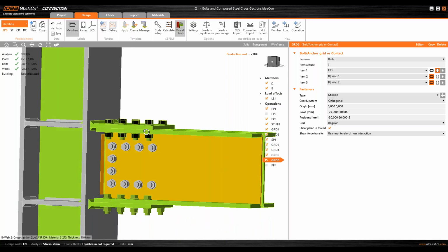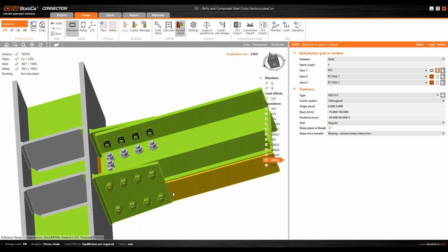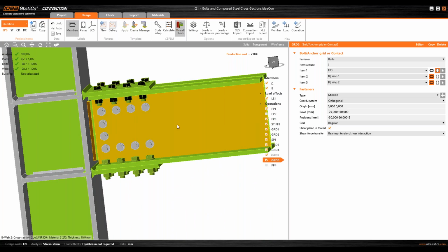In this case that I am presenting you, the fin plate operations, for example, I don't use it for the flanges because the reference point is not aligned with the center of the beam. But for example, in the case of the beam web, the fin plate operation is perfectly valid because the web of the beam is symmetric. So the plate by default appears in the center of the beam, so we can use it perfectly. There is no problem.